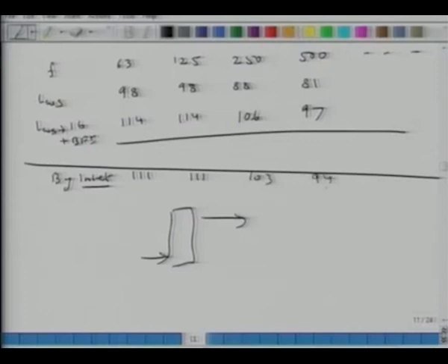And the other half is coming from the outlet. Why do I need to know this? Because if I have to do some ANC, active noise cancellation, I can place a small transducer in the inlet and it will correct the signals. That's what I'm saying. So this is the signature for a fan.